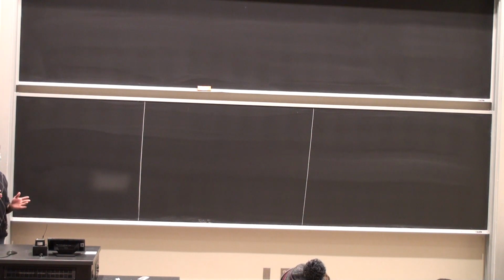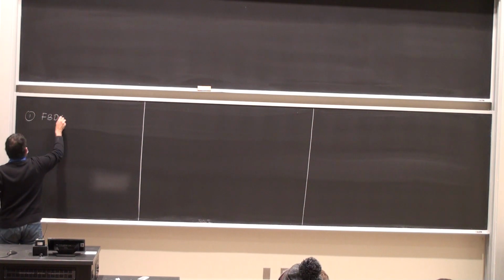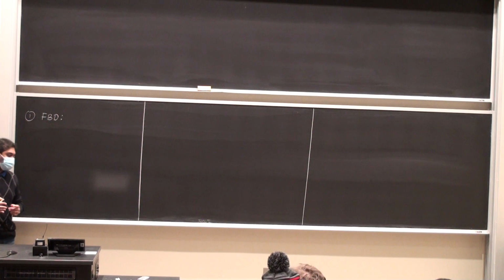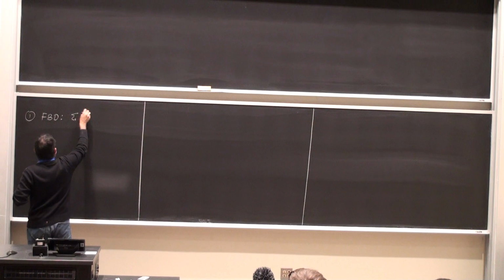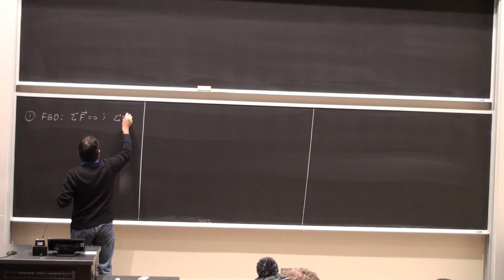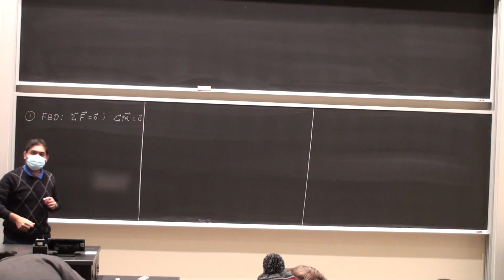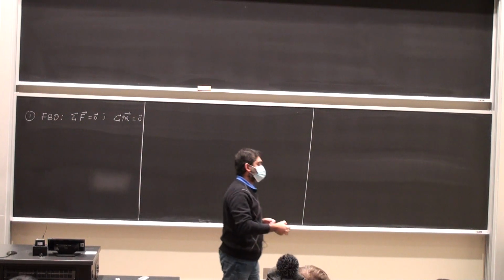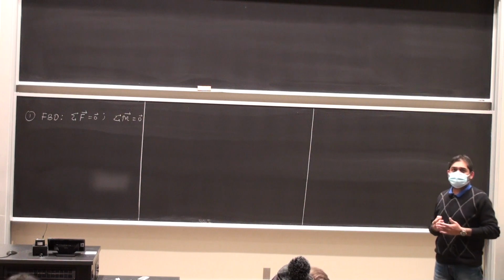Okay? First step in solving any problem is you draw the free body diagram, you do the static analysis. Right? You find out the reaction forces, reaction moments, and so on. Sum of forces, sum of moments. Right? All of them in vector notation. Then the next step is this. So the static ship has sailed. You go to the mechanics part of the problem.